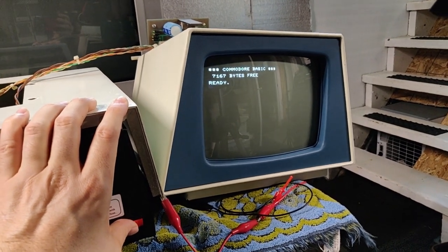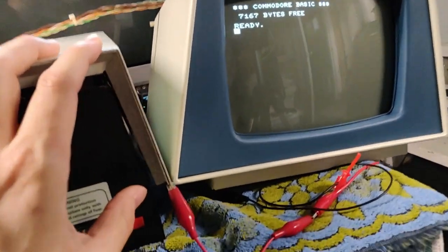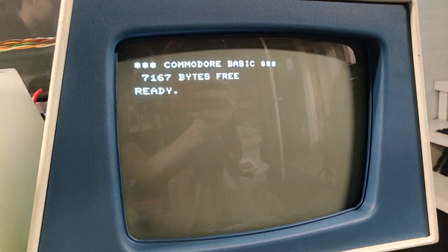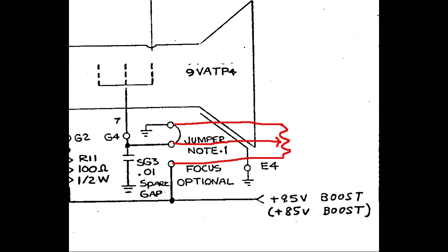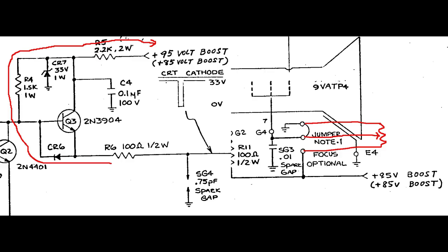So we started chasing ghosts for too much time. Out of desperation, I also suggested him to try to replace a lot of unneeded parts, as you can see on his video about the spot. However, finally I recollected that he tried to install a potentiometer on the focus grid, as I sketched here in this image. But this is a very easy path for the cathode current because the potentiometer just connects the 85 volts rail to ground.